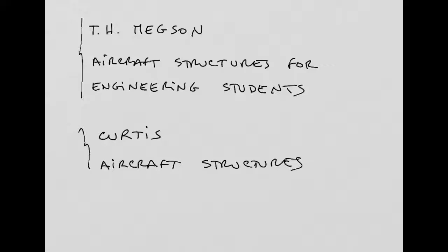So we have half an hour. If you don't have any questions on this, I will continue with transverse shear for the fully effective cross section. We did basically two examples, one for an open cross section, the other for a closed cross section. Of course, we are going to define more complex cross sections, for example the cross section of a wing box. So you have this airfoil shape, and this airfoil will have a skin.